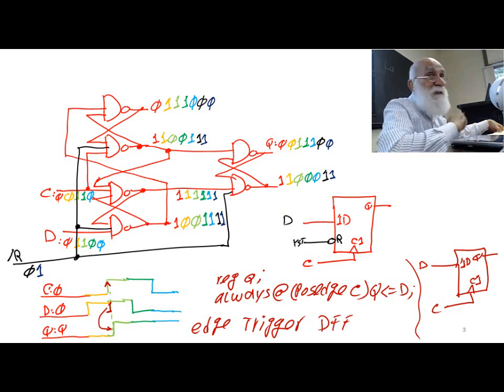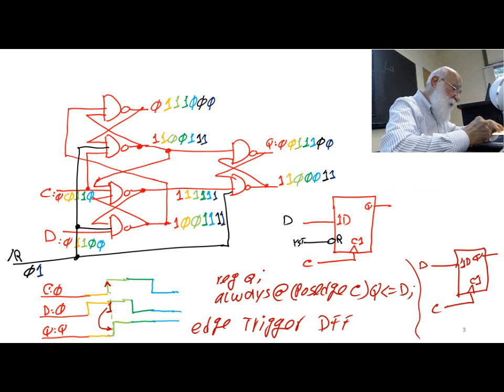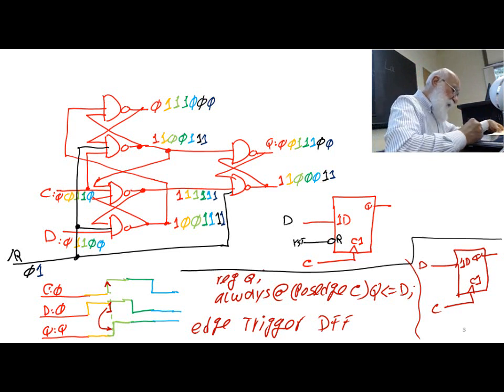Notice that I did not use the number 1 on the left hand side of my reset. Okay? Number 1 on the left hand side of the reset would mean that it's controlled by the clock. This is not controlled by the clock. Okay? It is called an asynchronous reset. And then I'm going to show the very long description for it in a few minutes.